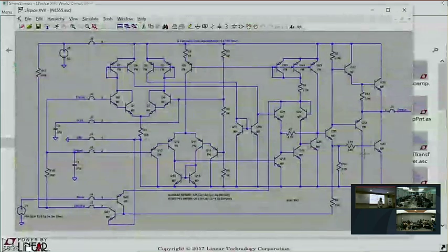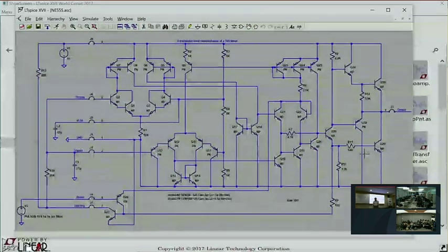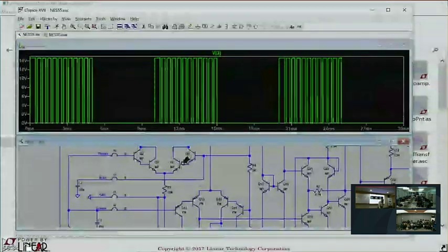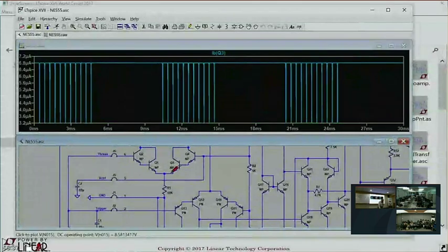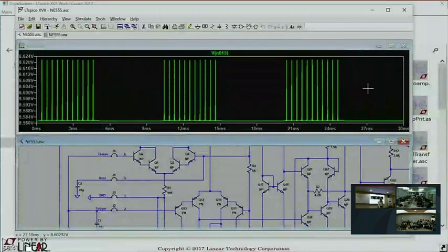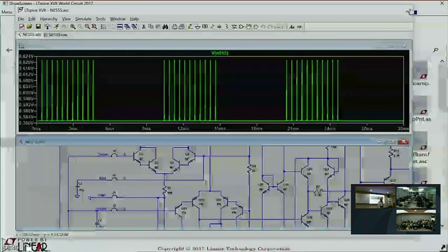There's a few IC schematics. This is a 555 timer, at transistor level. You can simulate this IC. You can plot every device current and node on the whole IC. Okay, and there's a few IC schematics, various industry legacy ICs, like a 741 op amp, a 308 op amp, 555, and a 1648 VCO.